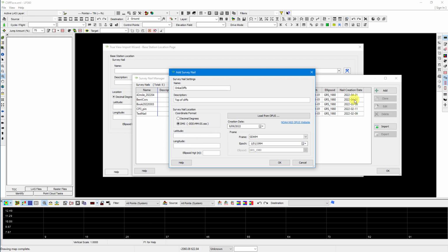So let's put in our coordinates. Our data came back as degrees, minutes and decimal seconds, so I've chosen to use that one. Now I need to put in the latitude, so minus 35 degrees, 9 minutes, 56.64479.